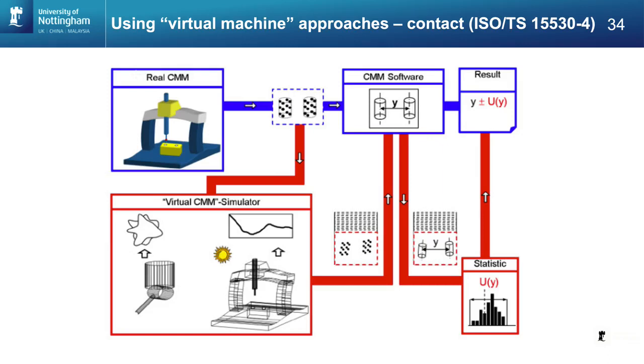And then once we know how the object is being measured, we have the measurement program worked out, then we can propagate all of the influence quantities through the measurement model many times. This is typically done several million times, which then gives us a statistical representation of the uncertainty of the measurement. It's what's called a Monte Carlo approach to uncertainty estimation.